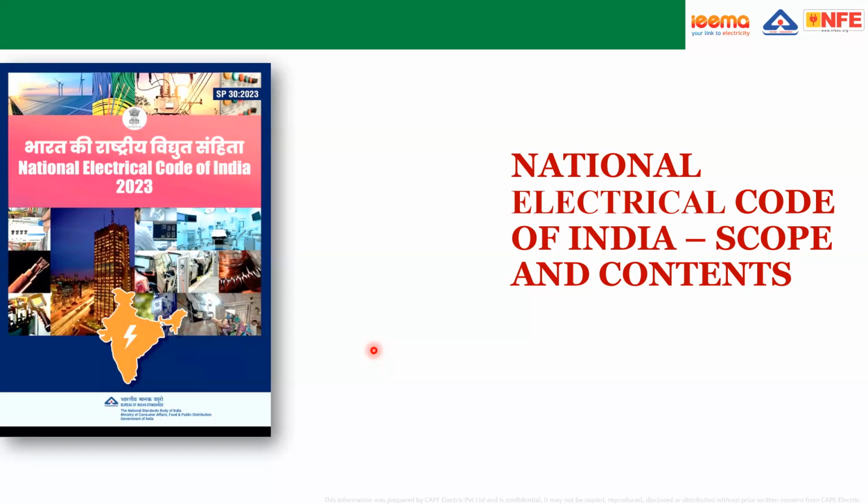Sir, in a TN system, why is RCD not required? Because the earth fault loop impedance is low enough to disconnect. The MCBs will work in case of an earth fault.